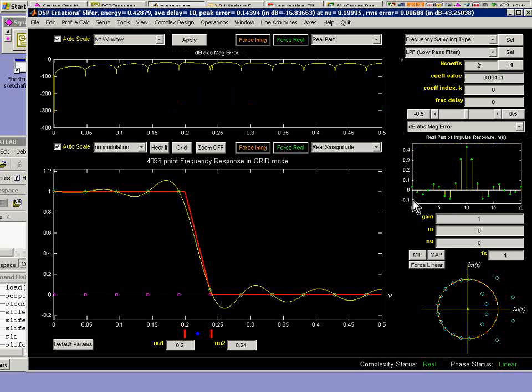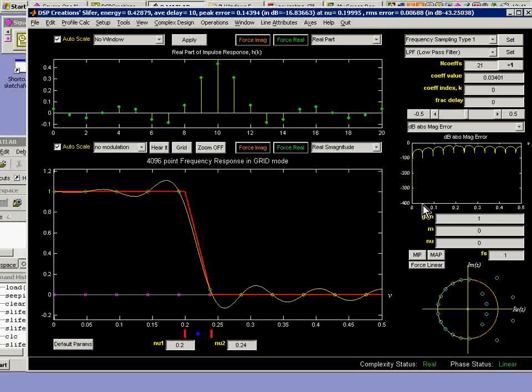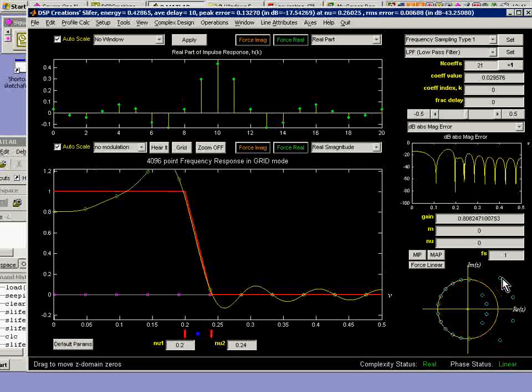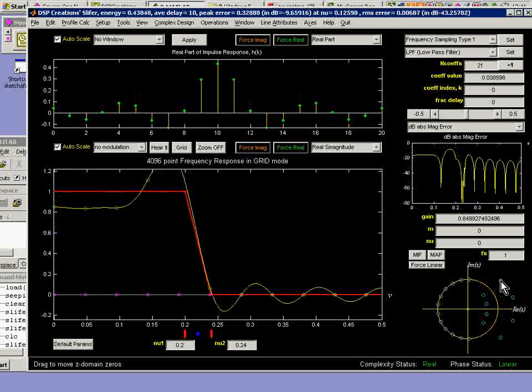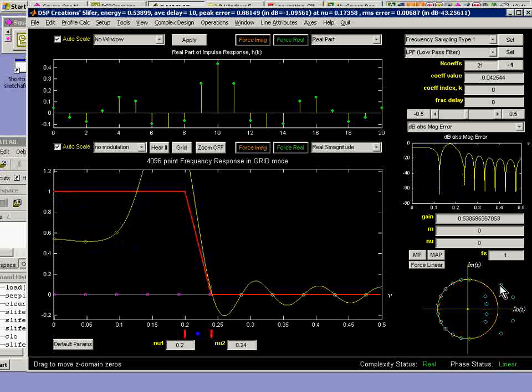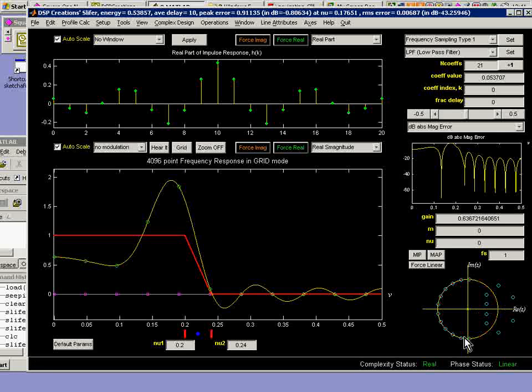Now, of course, this is on quite a small scale, and you might wish to toggle it into better visibility. You can do this by clicking on the vertical line here, and this then swaps position with what was previously in the narrow axis. You can even go further than that by exporting this information out for external plots. The final picture we have is the PoleZero plot. Now this is live. You can actually move these zeros around, although we don't claim that for this tool this is a very precise way to do any design of a filter, but it does show how everything interacts with everything else in the time domain, frequency domain, and the Z domain.